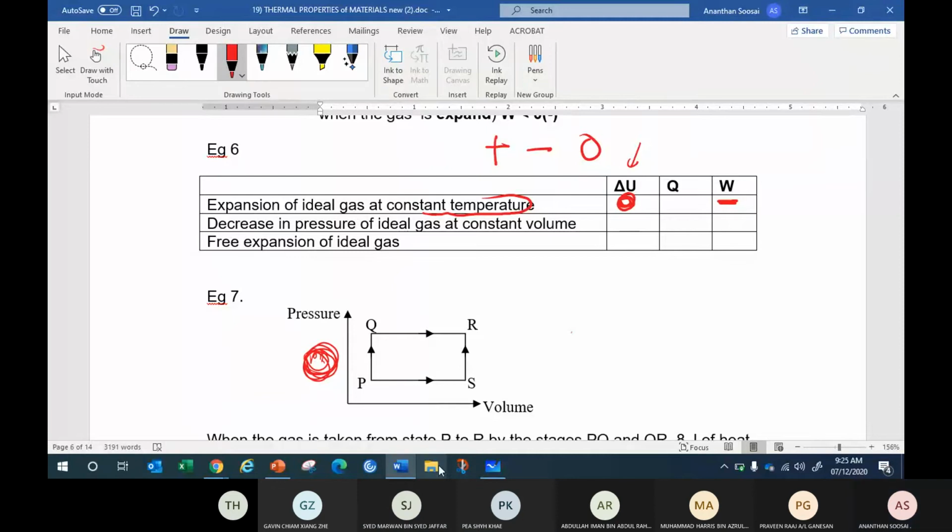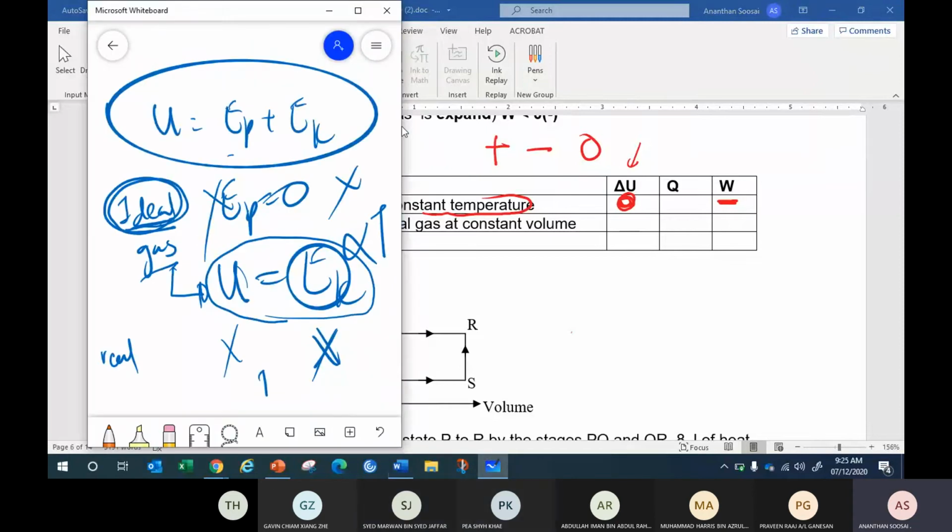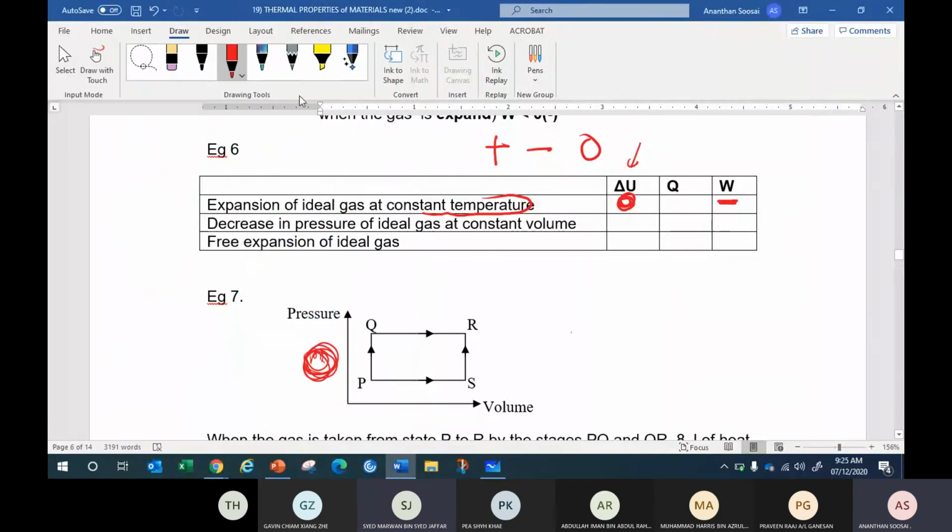But what is meant by work? What is the work formula? Force times distance traveled, right? Is there force applied and the gas expands? Yes. The piston moves up. Gas expanding means gas pushes the wall, right? The force is applied, distance traveled. Is there any work? Yes. The work is not zero, it has a value. In this case, work is negative. Why negative? Because expanding. Expand means negative, because you give a negative effect to the internal energy.